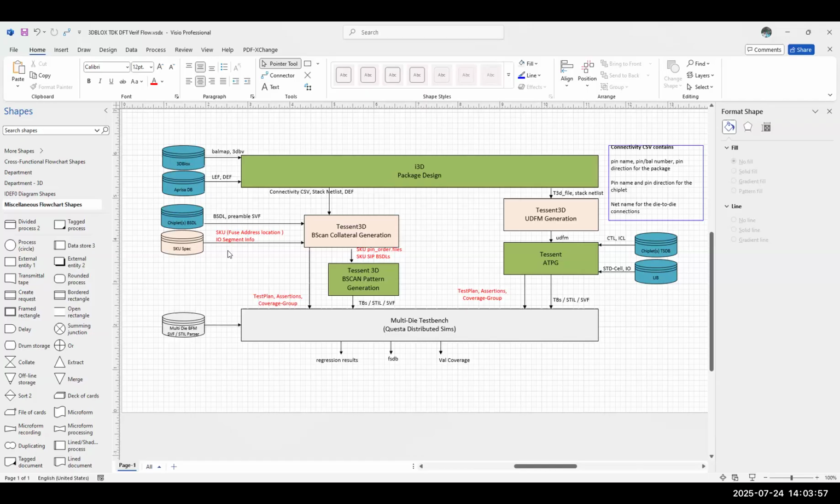So as far as a fuse program mode, we could just have a subset of pins that are used for that. Then you need to provide patterns and instructions on how to use those, but at least in the format we have this information, right? I think it's necessary, Tony, but not sufficient. What Bala was thinking is the next level, where the information is a fuse location. I'm not sure how location is represented, as an instance or as a number, but anyway, here is the identifier for the fuse, and for this segment, the address X of that fuse needs to have value Y.